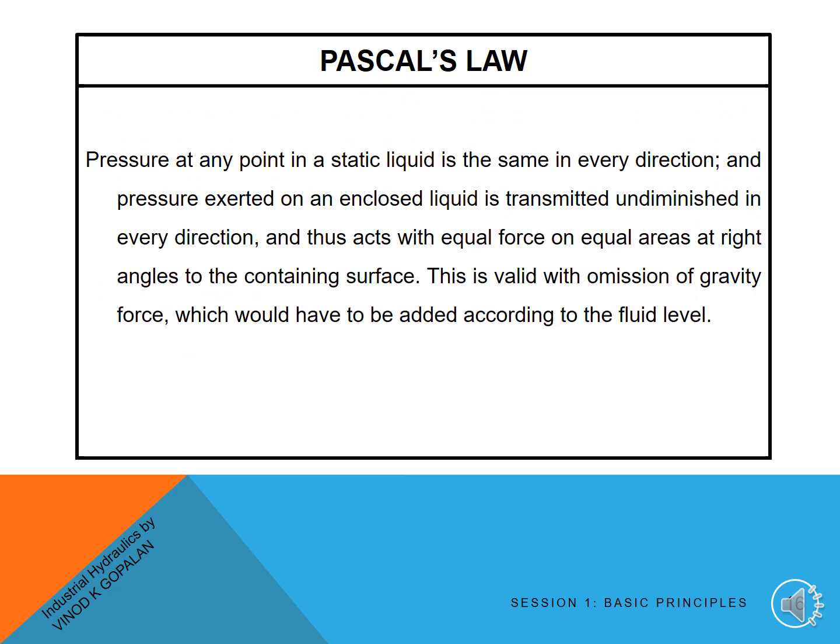Pascal's law. Modern hydraulics works on this principle. It states that pressure at any point in a static liquid is the same in every direction, and pressure exerted on an enclosed liquid is transmitted undiminished in every direction, and thus acts with equal force on equal areas at right angles to the containing surface. This is valid with omission of gravity force, which would have to be added according to the fluid level.